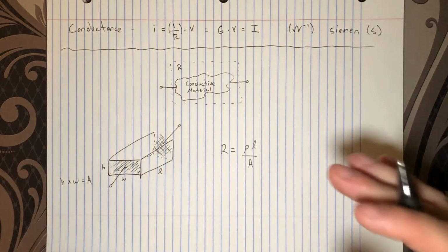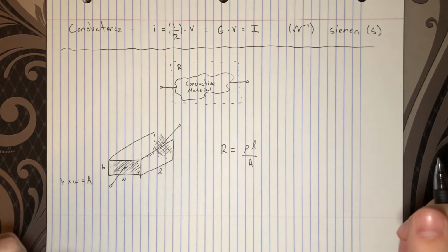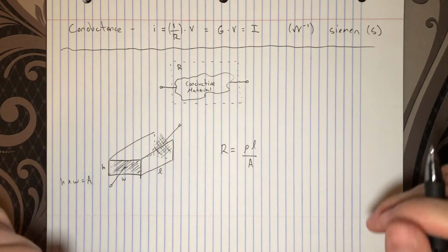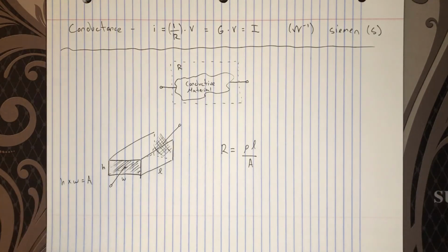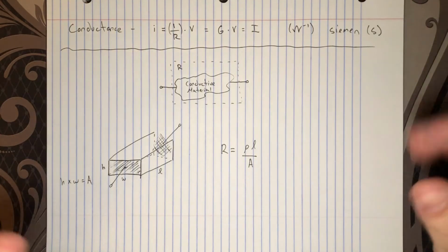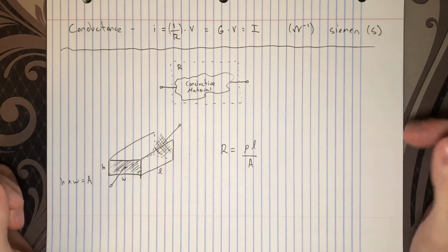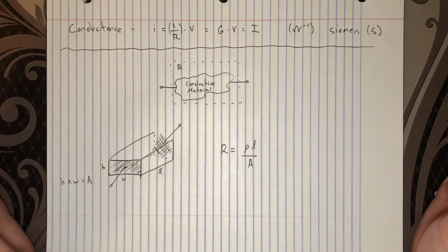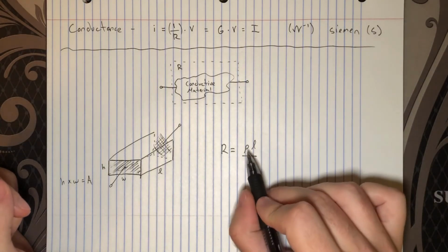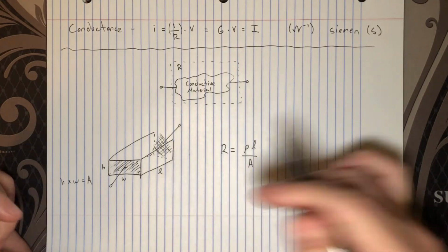And so we know what voltage and current are, and let's say we have the ability to source these things and then measure voltages and currents. Well, then, of course we know how to make materials, and we can measure them and understand their dimensions. So as long as we have control over a voltage and a current, we can measure the resistivity of any material.